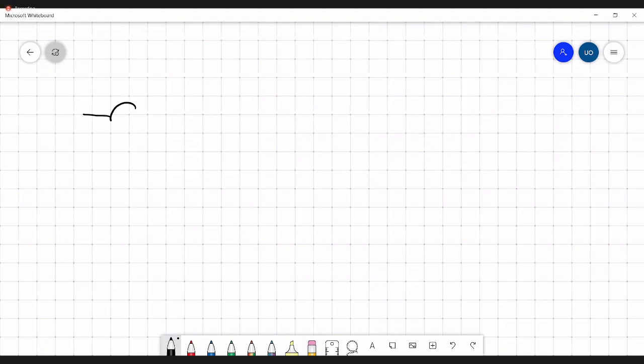So this is the original replacement. This is A, B. The actual diode is simply across A and B. Now we replace it with a simplified model, and we have a fixed DC source of VB, along with the ideal diode.